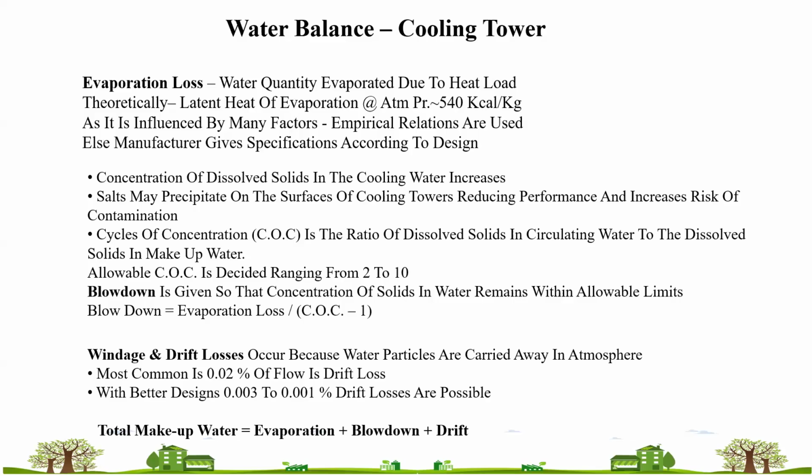So that COC has to be maintained. That TDS level has to be maintained. To control that TDS level, you need to give blowdown. Blowdown means removal of water or removal of salts from the system. Blowdowns are typically given in cooling towers and in boilers to avoid the risk of contamination or failure caused by these salts.